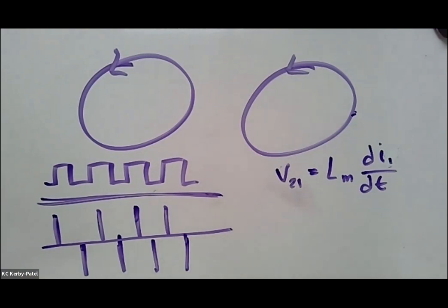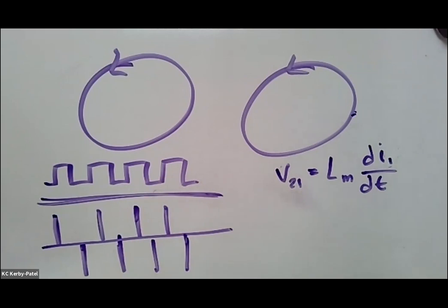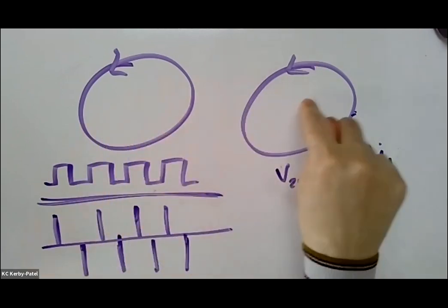And this is just because the high frequencies are the ones that contain the pointy features of your signal. If your high frequency content gets distorted or messed up in some way, it makes it harder to distinguish a 1 from a 0. And if you have a lot of high frequency content, then it makes it more likely to talk to the circuit next door.